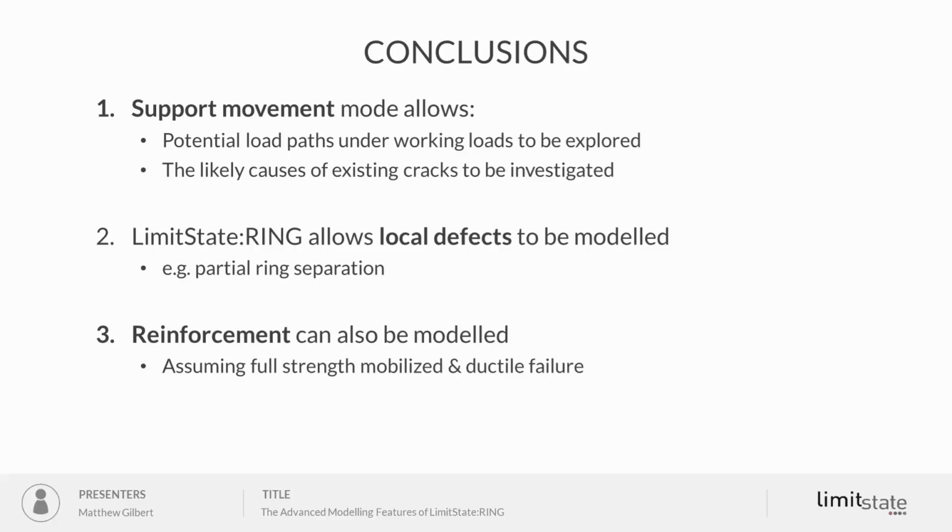And lastly, we looked at reinforcement. Bear in mind that you assume that full strength can be mobilised and a ductile failure, so it needs to be used with care, but if you use it carefully it can be very useful in giving you an indication of the likely benefit of any given reinforcement programme.